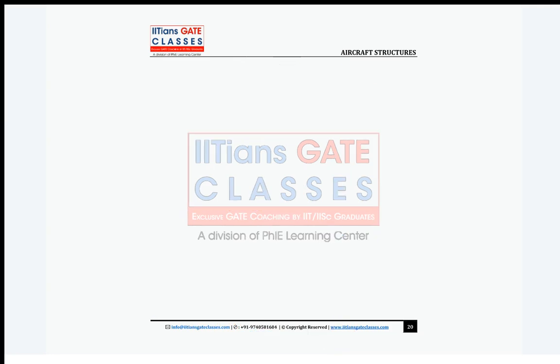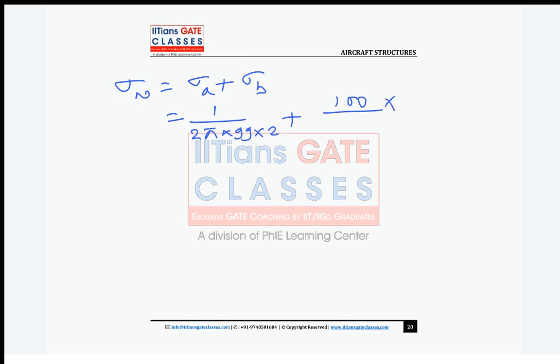Again, I'll write, I have the blank space. So sigma normal is what? Sigma axial plus sigma bending, and sigma axial is 1 upon 2 pi r mean. So it is 1 upon 2 pi into 99 into t, plus 100 into 100, which is the external dimension, upon 2 pi into 99 cube into t.